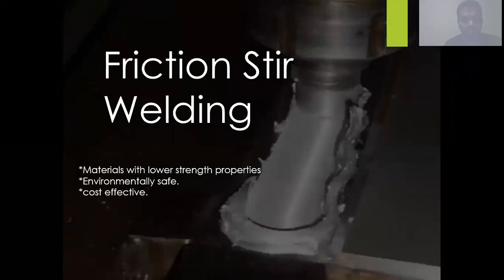In the 90s, it was discovered that it is possible to use the milling process to produce a welding joint on an aluminum plate by using the heat produced from the milling friction. This application was suitable on materials with lower strength properties. It was noticed that, unlike traditional welding methods, this process did not produce gases, so it is safe and reduces costs because there is no need to add filling materials to produce welding joints.